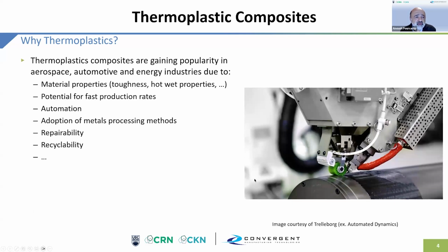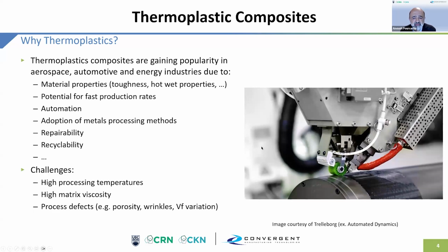Technically, this is a presentation to the Thermoplastic Committee, though I can see that we have quite a few other attendees, which is lovely. So I'm not going to go into why thermoplastics in any great detail. The one that I think really is relevant to the simulation stuff that makes it different is that there's a huge interest in fast production rates and, of course, automation. In terms of challenges that then lead into process simulation issues, we have high processing temperatures, and that means we have a fairly small window from where, say, the viscosity of the matrix is low, and you get into degradation problems. And of course, what we're trying to do is avoid the defects that detract from the value of the material.